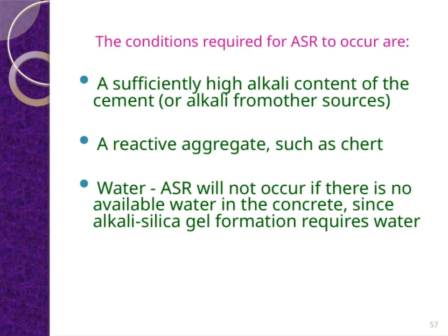So, to understand the conditions that lead to alkali-silica reaction, or ASR, we need to look at a few key factors. First, a sufficiently high alkali content in the cement, or alkali coming from other sources, is essential. This alkali acts as a catalyst in the reaction process. Next, we need a reactive aggregate, such as chert, which contains silica that can react with those alkali ions. And finally, water is a critical component.